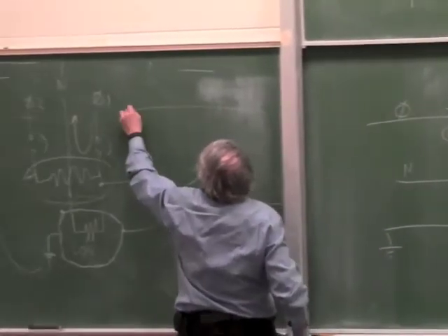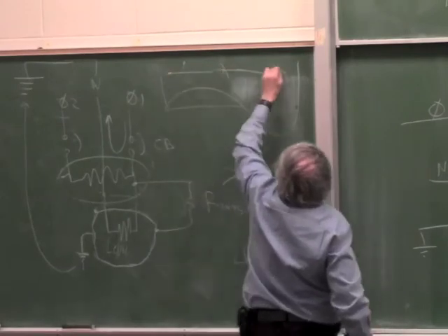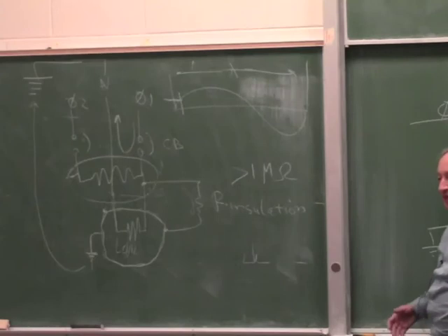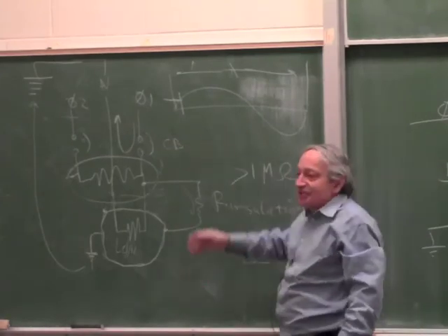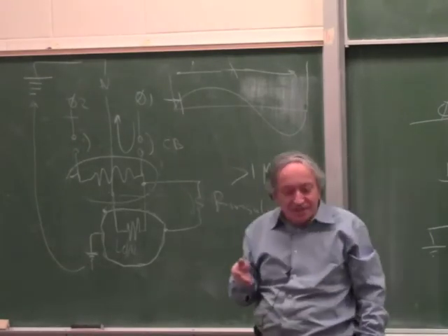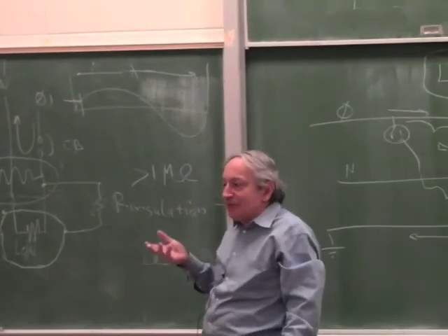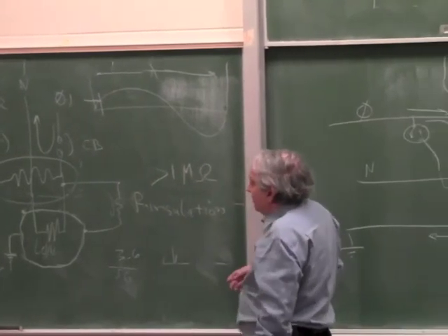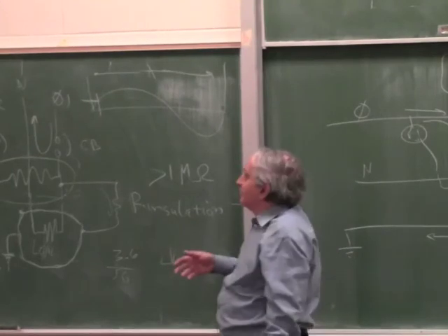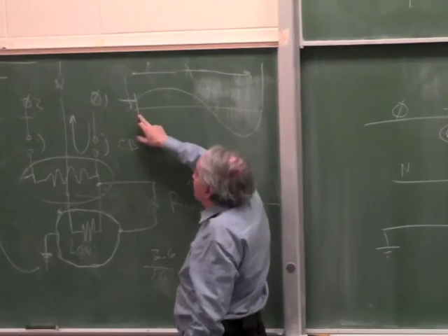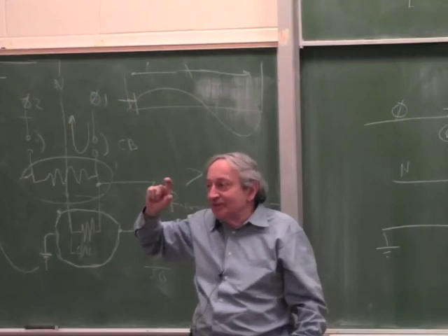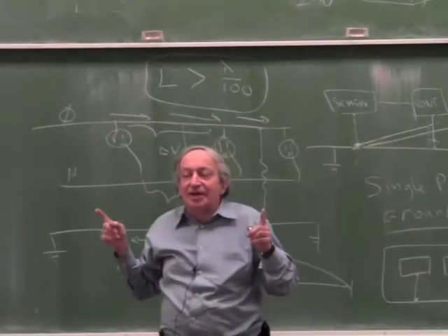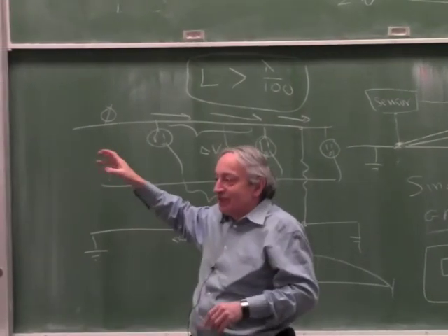Because if you have a sine wave, and this is lambda, at 1% of lambda, there is already a significant voltage, because 1% of lambda is 3.6 degrees, right? 360 degrees, 1%. 3.6 degrees, sine of 3.6 degrees is probably 0.05, it's around 5%, right? Because do it in radians, 3.6 degrees divided by 57, so let's say it's 1/15th of a radian, so this would be about 6%. Roughly, you can look it up in your calculator, but if this is 1% of the wavelength, this is going to be like 5-6%, so it's already significant voltage. So that's why this is kind of a good guide. If you're dealing with items or wires which are 1/100th of the wavelengths or more, you have to treat it as RF. So there are different rules of design.